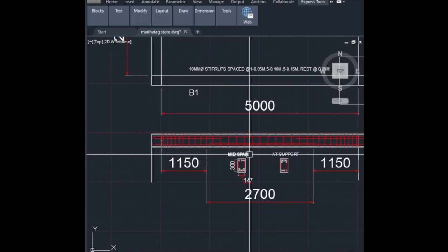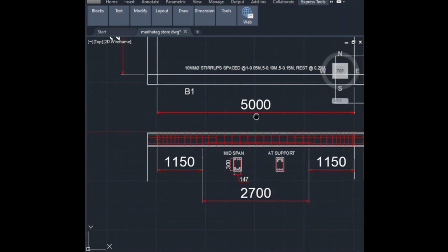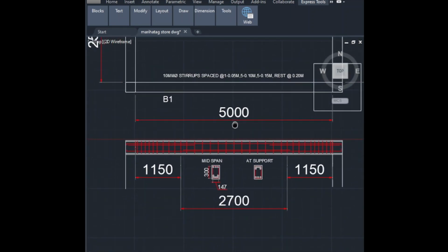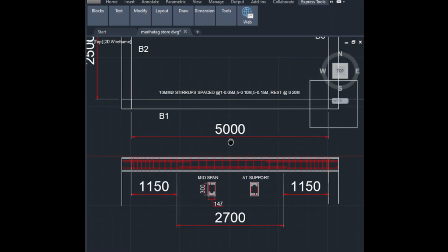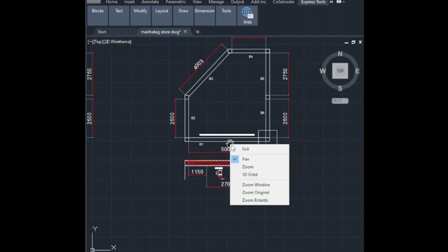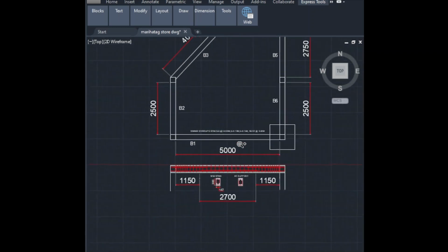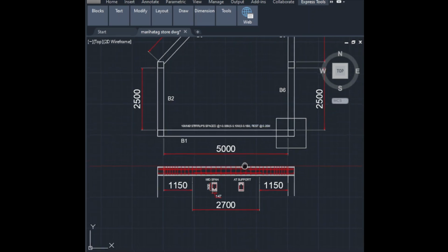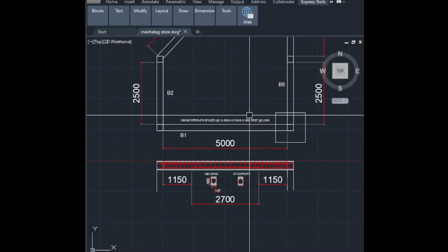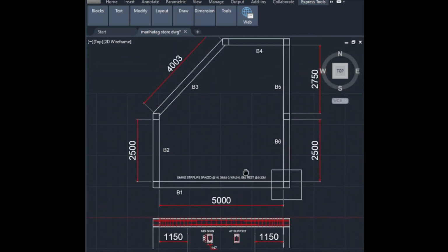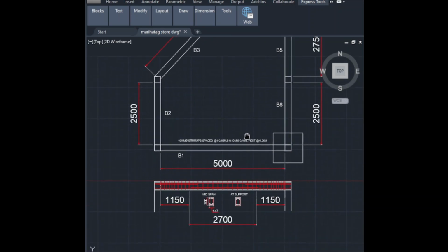Actually, guys, in the actual plan, there is already a cutting list of the steel, so you just refer your quantities there. But do not copy directly, because some cutting lists are incomplete, so you have to understand what you are going to put in your quantity. You might be losing quantities if you do not check that, or you might be putting in more bars.